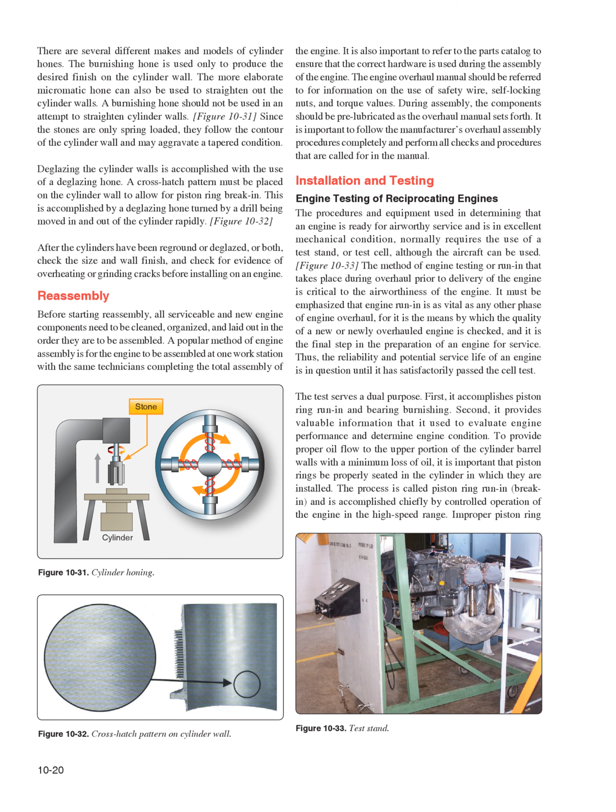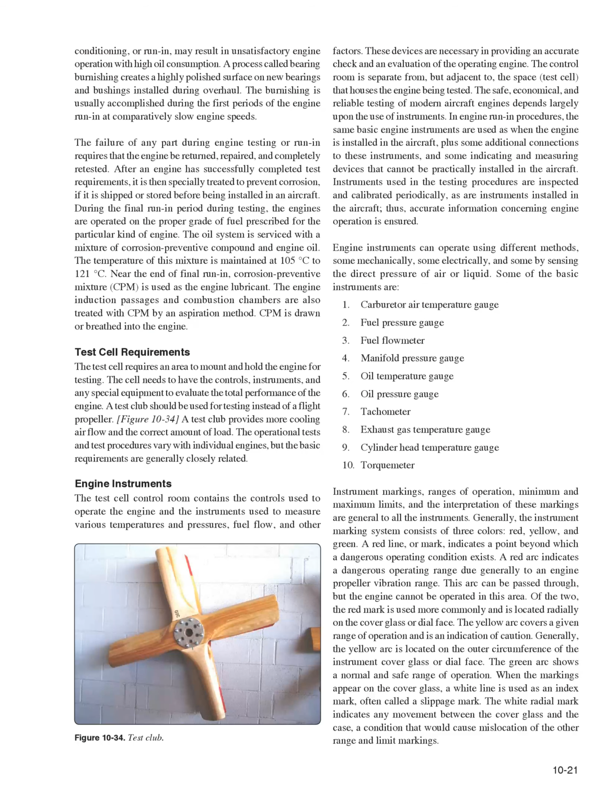To provide proper oil flow to the upper portion of the cylinder barrel walls with a minimum loss of oil, it is important that piston rings be properly seated in the cylinder in which they are installed. The process is called piston ring run-in, or break-in, and is accomplished chiefly by controlled operation of the engine in the high-speed range. Improper piston ring conditioning, or run-in, may result in unsatisfactory engine operation with high oil consumption.